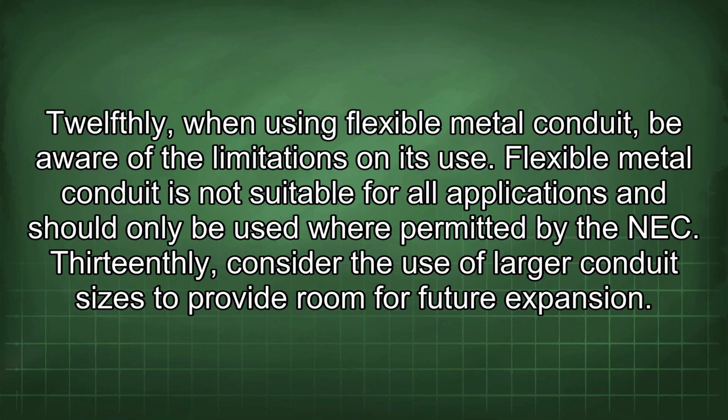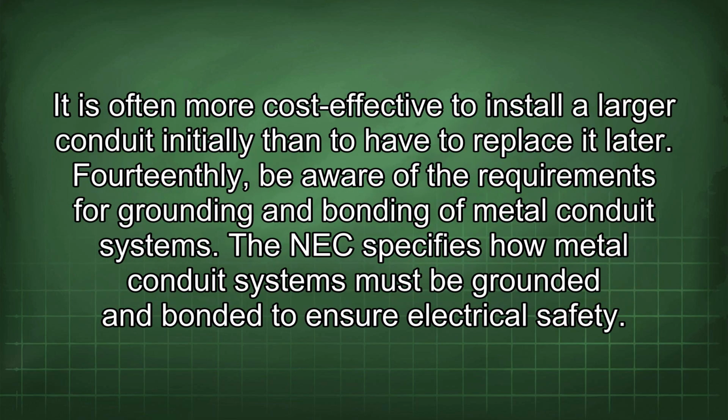Flexible metal conduit is not suitable for all applications and should only be used where permitted by the NEC. 13thly, consider the use of larger conduit sizes to provide room for future expansion. It is often more cost-effective to install a larger conduit initially than to have to replace it later.